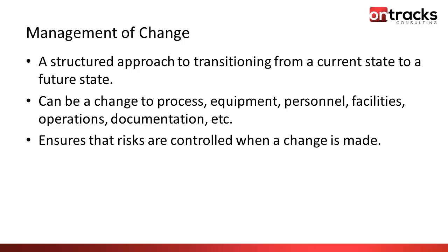So some examples of changes would be a change from original design specifications in some equipment, a change to a process, changing operating conditions so that they're outside of the approved operating range. It might be changes to a material or specifications. It might be a change to the way that critical activities are done, changing personnel, or changing your organizational or reporting structure. So there's definitely a lot of scope for it outside of the traditional fields of changing equipment.